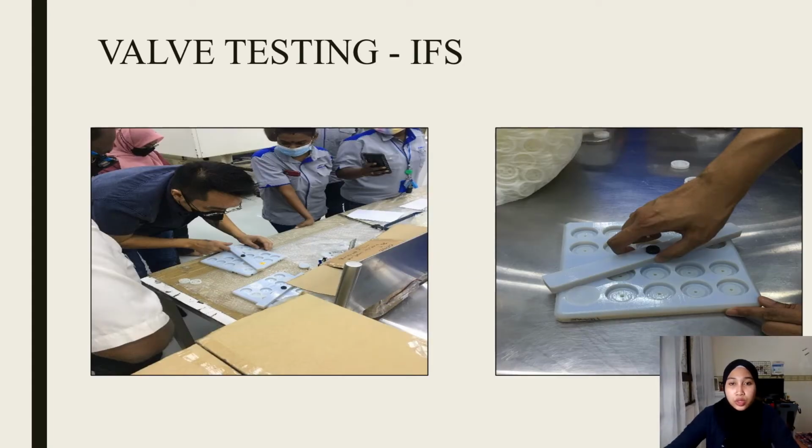Next, this figure shows the valve testing process. The precaution that needs to be taken after injection is that a valve needs to be cooled down for 10 minutes before proceeding to the trimming process. Otherwise, the valve part might deform due to hot temperature after injection.